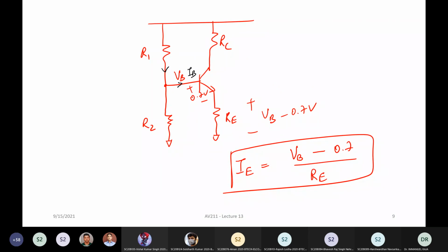So if you design it for 1 milliamp, you'll at least see either 1.05 milliamp or 950 microamp or something like that, plus or minus 5-10% you will see easily. But that is still more acceptable than something completely uncontrolled, like allowing the BJT to run freely. Is it clear? Now let us build the whole amplifier around this.